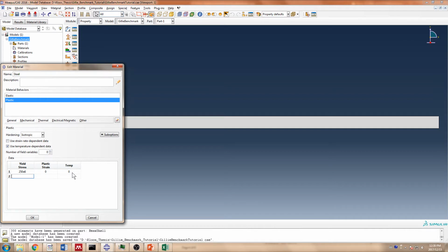Then the yield stress at 1000 degrees is 0, but you can't put 0 in here because for the FEM model or in a matrix, you can't have a zero yield stress. So we're going to put in a very small yield stress, which is essentially 0. And that's also a plastic strain of 0 and 1000. You can give much more complex material models here by just using a full table with many more plastic strains. So if you have a more curved elastic plastic relationship.